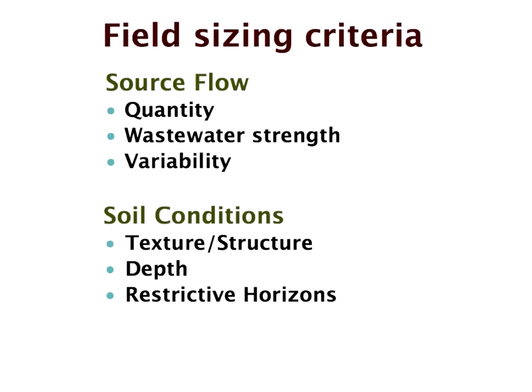And soil is the most critical thing, as you'll hear me say again later on. When there's a mechanical error of some type, you can generally fix it, whether it's changing a pump, increasing a field size, or taking a zone out and putting in another zone. But if you've got a basic error in soils, you're in trouble. It's very, very difficult to repair after it's been installed.